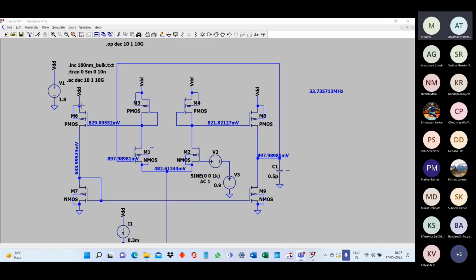Okay, so it's just too low, right? Because VSG is too high. No, that is okay. VSG is like that because the W by L is also low, right? So we have increased the L also significantly. So that will be the case. That is okay. So now you can see that the overall error is 2 millivolt. Earlier it was 15 millivolt. Now it is 2 millivolt. So pursuing the similar strategy, we can go ahead.